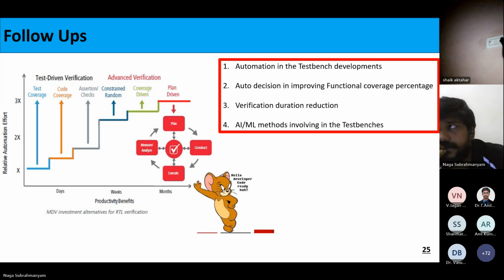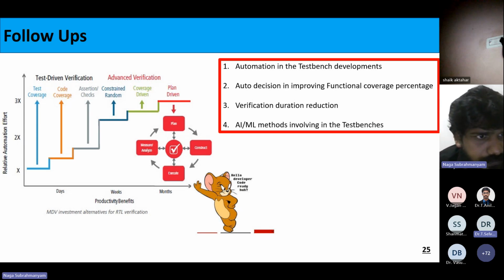Every time I'm putting 0 only. When the mux is verified, if the selection line is 0, we check the output is equal to the 0th input. If I put the selection line as 1, we can understand whether the output is the first input or not. So if I always put 0, only one portion of the mux is verified, right? That is 50%. All those things we will verify in code coverage. In your plan items, if you verify all those things, your test coverage is 100%.